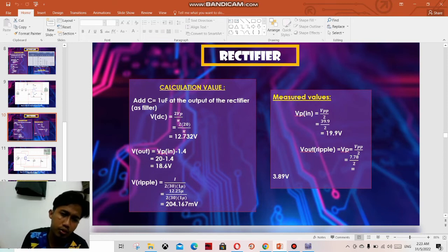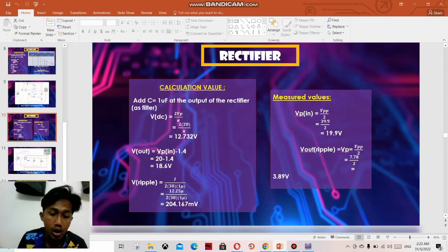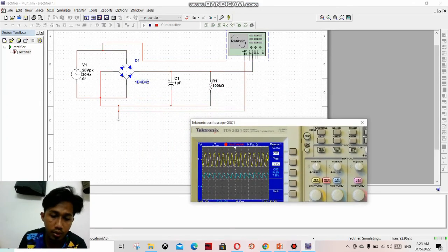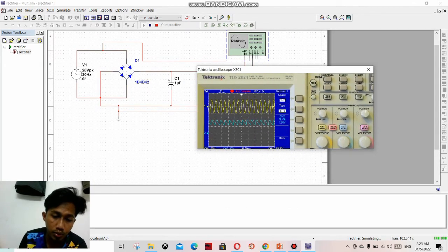So for the full bridge rectifier, the main component is the smoothing capacitor, to convert the full wave ripple output of the rectifier into a more smooth DC output voltage. The blue plot on the waveform shows the result of using a 1 microfarad smoothing capacitor across the rectifier.